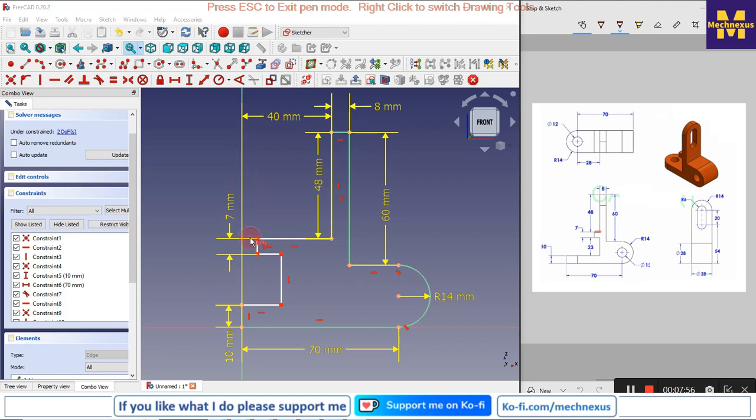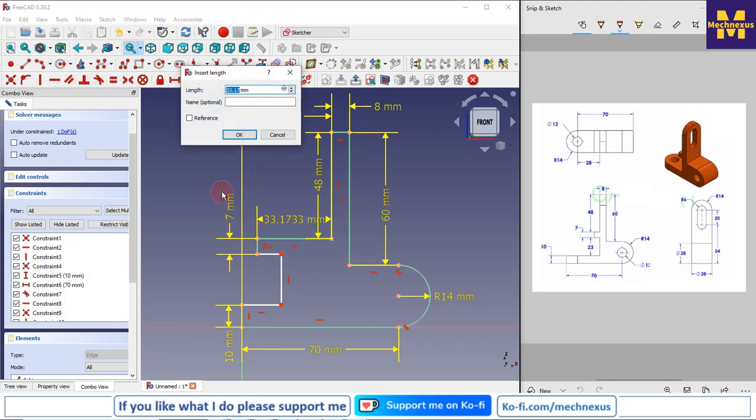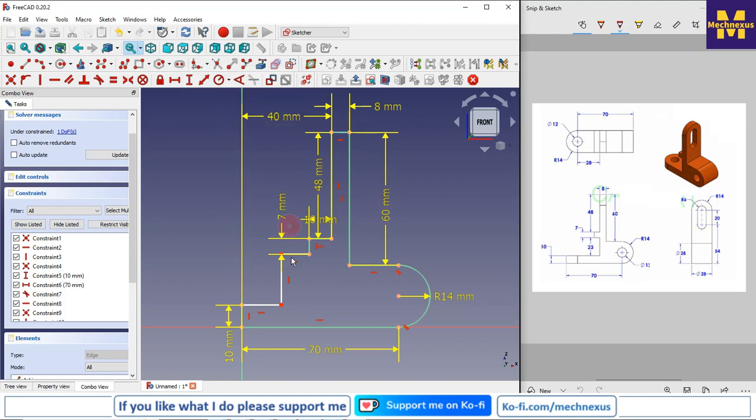So I will select this line and I will give the horizontal dimension. This is the 7, so I will consider it as a 10, and I will move it to the inside, and I will make this point and this point vertical.